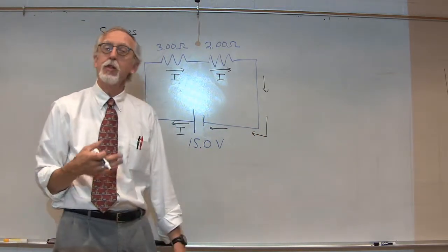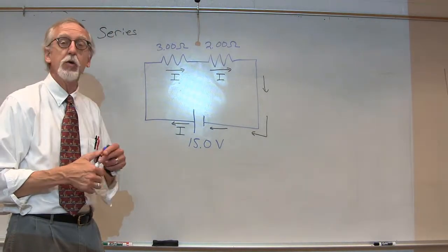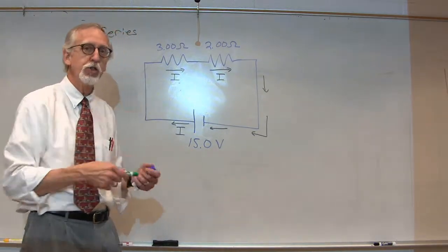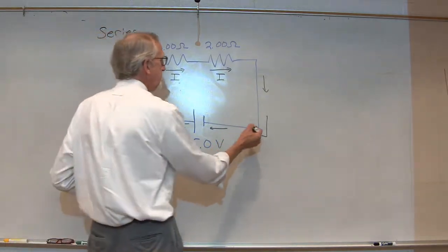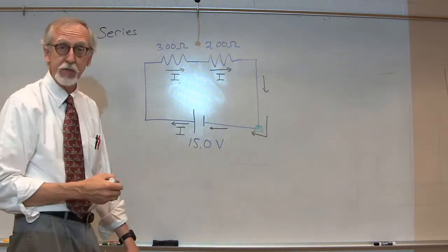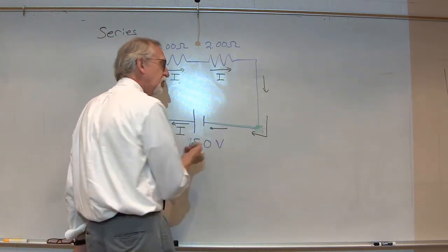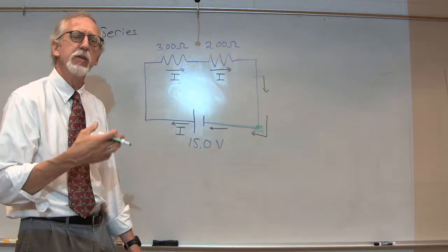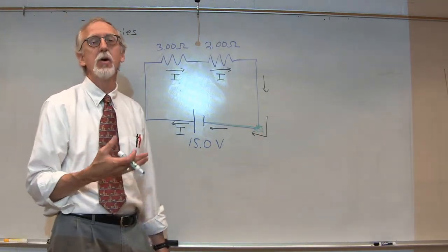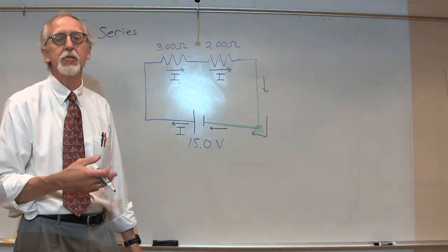Now, let's apply the loop rule and see if we can figure out what that current is going to be. So, to apply the loop rule, we have to choose some point and go around a closed circuit around that loop. So, let's pick, let's say, this point here, and we will go around this clockwise. Now, clockwise, we're coming along this way. We are making the assumption that the wires in these circuits have zero resistance, extremely low resistance relative to anything else.